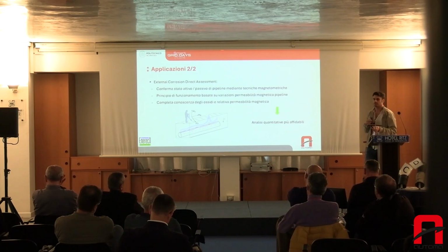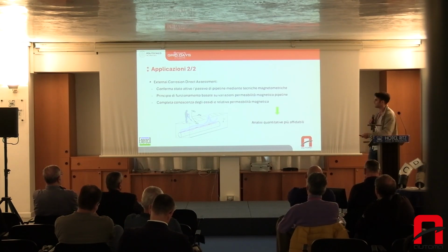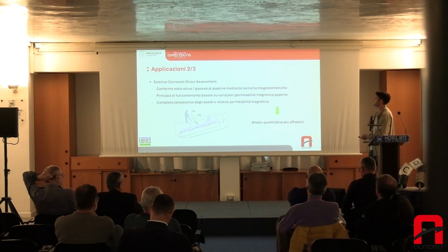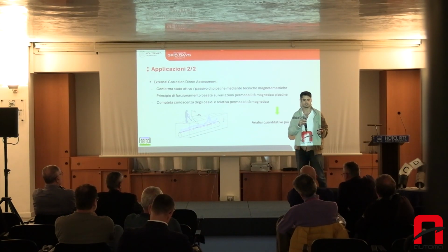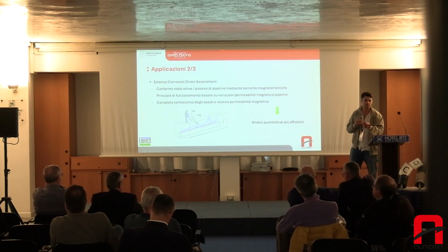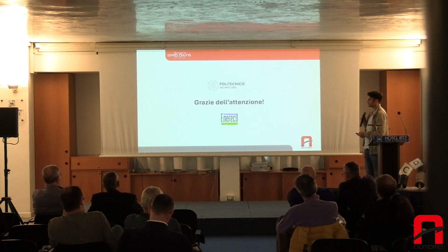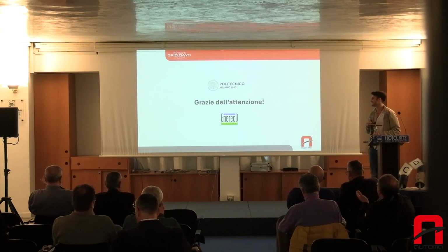And then the study basically showed what the materials are formed on a tube protected with this potential. And so you can use the values of magnetic permeability in the various stages to carry out more reliable quantitative estimates to see if a defect on a coating is active or passive, and actually what the most reliable corrosion level is. So I'm done. I was very, very brief. Thank you very much.